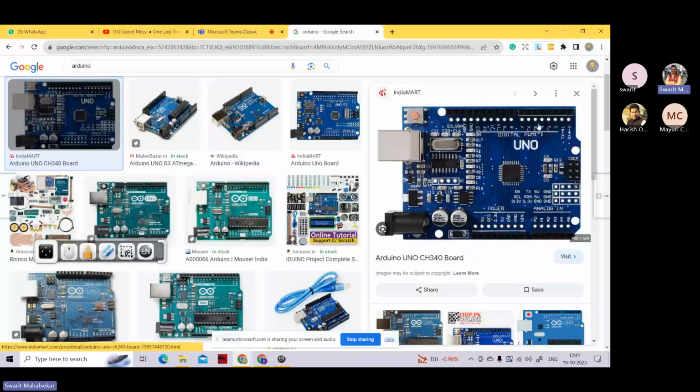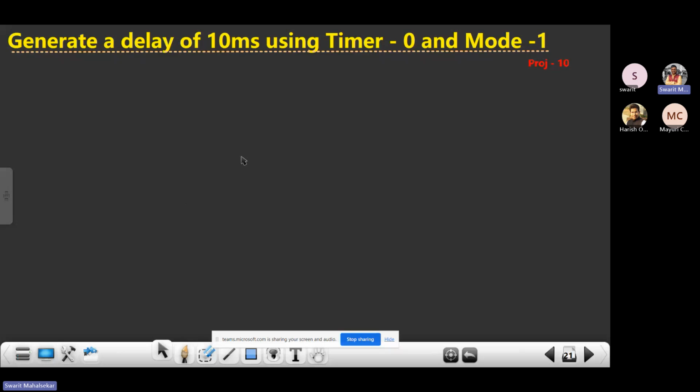You see pin number 3, 6, and 5, all these particular pins are responsible to create a PWM signal, through which you can control the motor, right? So basically the same concept is used over here. We are actually trying to create the same kind of logic. We're going to create a square waveform. Basically we are going to create a kind of PWM logic. So it is somewhat similar to that only. I hope you are getting me.